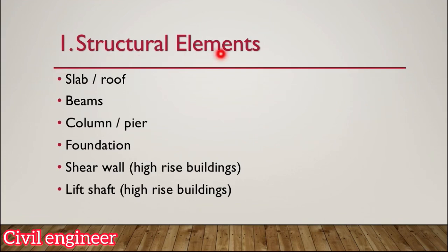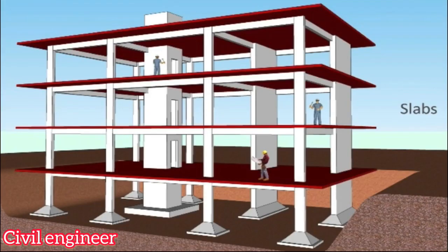The structure elements. These are the basic elements of any structure. By definition, the systematic way of connecting all these elements to withstand the applied load or action is called a structure. Now I will share a basic frame structure identifying all the structure elements. The frame structure itself comprises beams and columns. In this picture, you can see it's a 3-bay by 1-bay by 3-story frame structure.